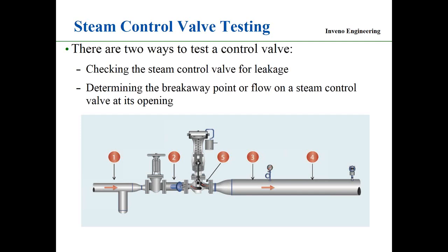Well, the thing about it is that that's a common problem, but what we do is penetrate the insulation with a small hole we call test plug. So you make an opening in the insulation so the probe can go in and make contact with the line. Once the test is done, then we plug that hole with a plug we call test port plug. Okay. And then let's see, how do you recommend testing or inspecting fixed orifice steam traps?